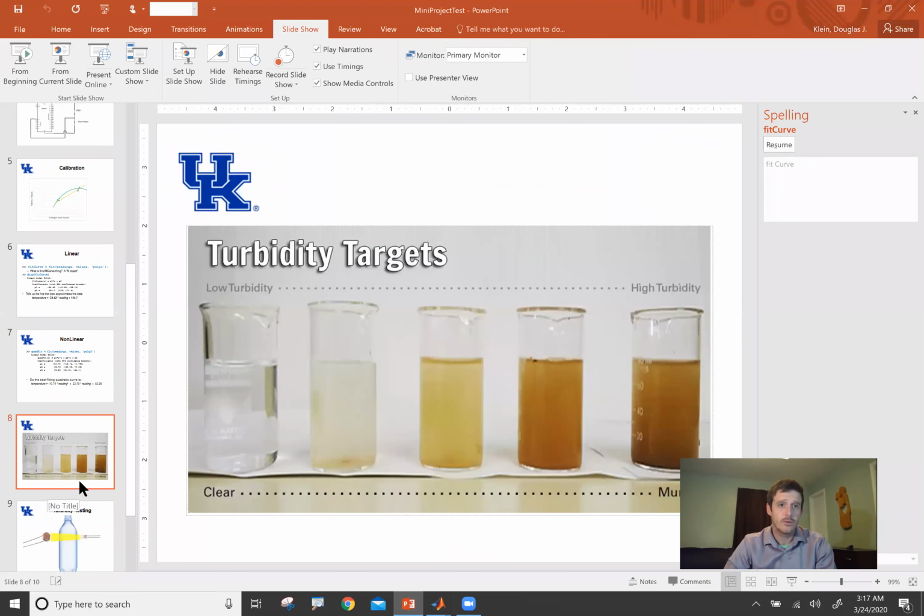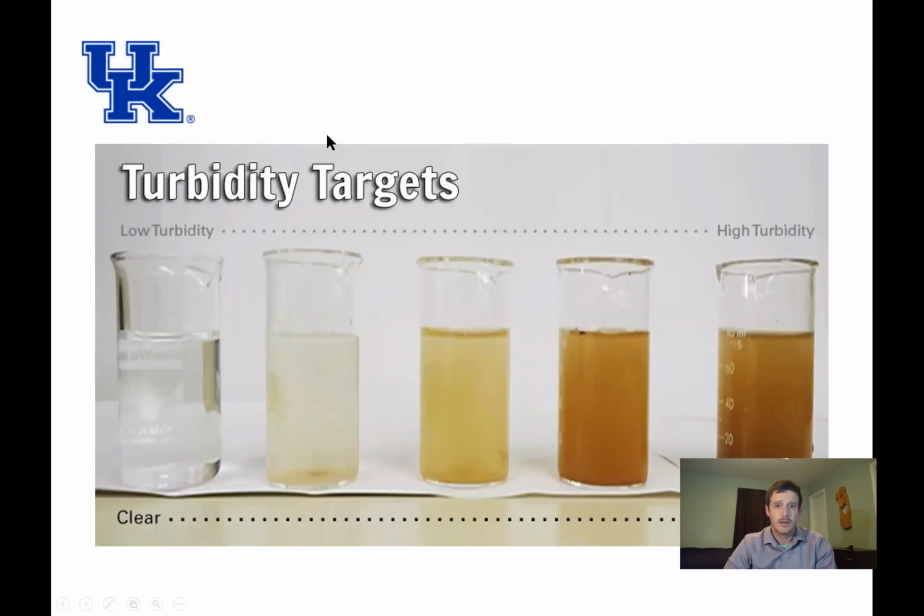And so we could also do the exact same thing for turbidity here. What turbidity is, is really just cloudiness, right? I can very easily put what clear water is, and I can try to develop a test situation over here. My thought is creamer, or milk. We're taking regular water, putting in 1 scoop of creamer, 2 scoops, 3 scoops, and 4 scoops, or whatever your dirty agent is.